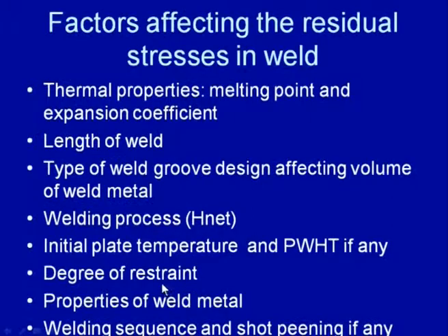Then the degree of restraint, how firmly plates are being held in position during the welding, will also affect the magnitude of the residual stresses that are being developed. In general, the greater the degree of restraint, the more residual stresses will be developed, because the contraction which will be occurring during the cooling phase will be restricted if the degree of restraint is too high.